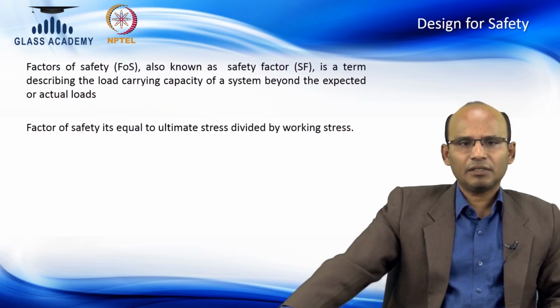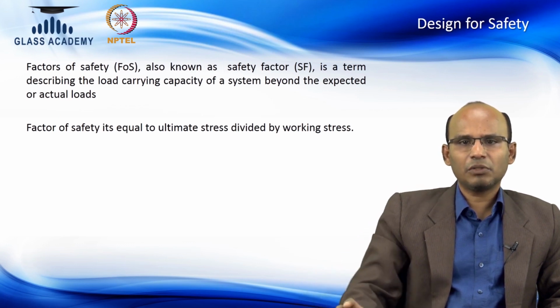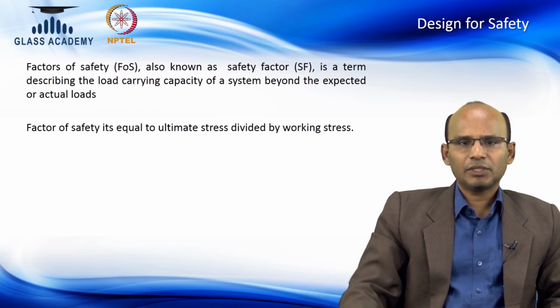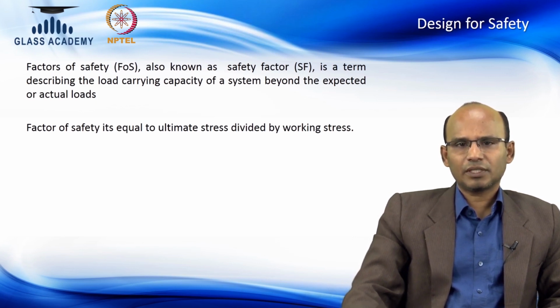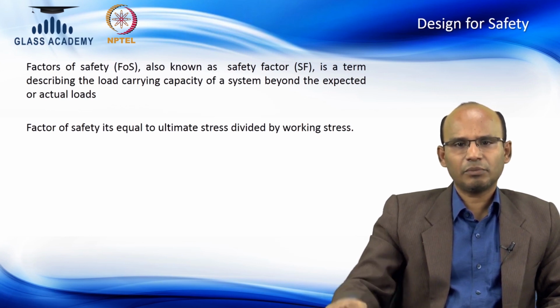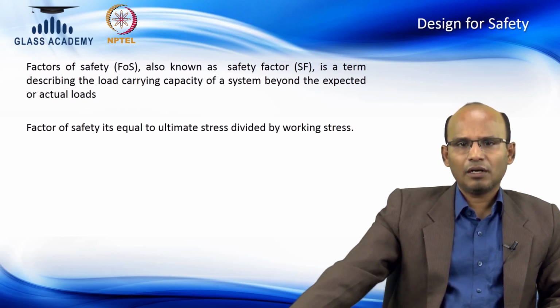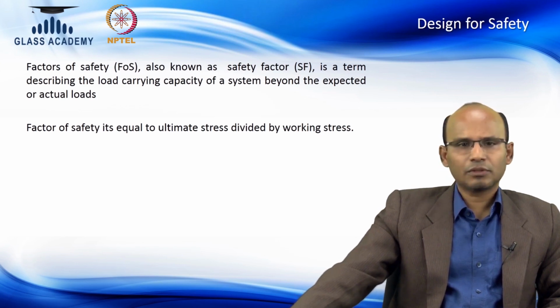Factor of safety, as typical to any other steel design or concrete design, is applicable to facade elements, being glass, cladding panels or framing elements as bracket detail. The safety factor for framing elements is generally 1.5 times, and for glass elements the safety factor is much higher, like 3 or sometimes 5. It depends on the glass types or which standards are being used.